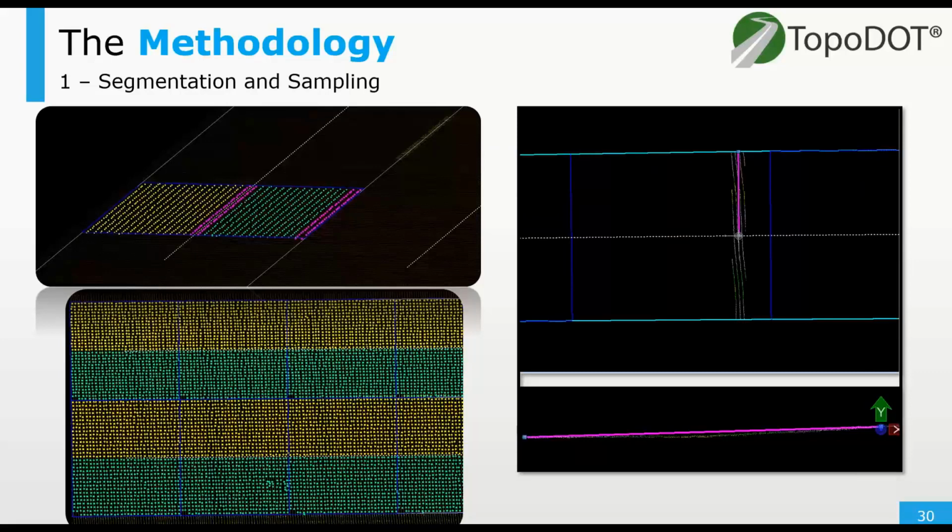So to start, we need some type of boundary information or boundary lines that provide the best approximation of the ideal lane line. And since paint stripe lines are least traveled, they provide an excellent reference for setting up an ideal lane surface. And keep in mind, paint stripe lines are going to be the easiest to extract out of the topography tools, so that's always a bonus.